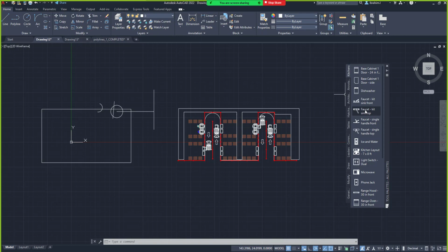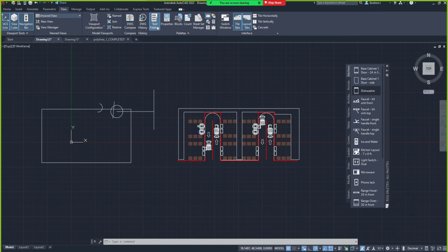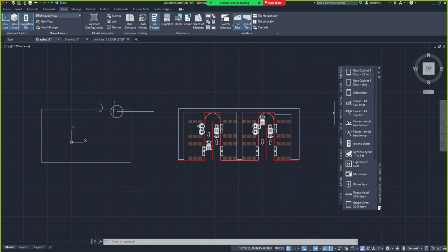Are you with me? So if I'm doing more of architecture, all the tools will be customized for my architectural field. But as a professional, even when you install the standard AutoCAD specialized software, the full software, I can actually customize my own workspace myself. I do that using the View section, using my tool palette. Under my tool palette, I have all these tools that have been created. Where are these tools created from? I can delete them. I can undo them. I can remove the panel. I can decide to close them. These are different palettes that are added here.